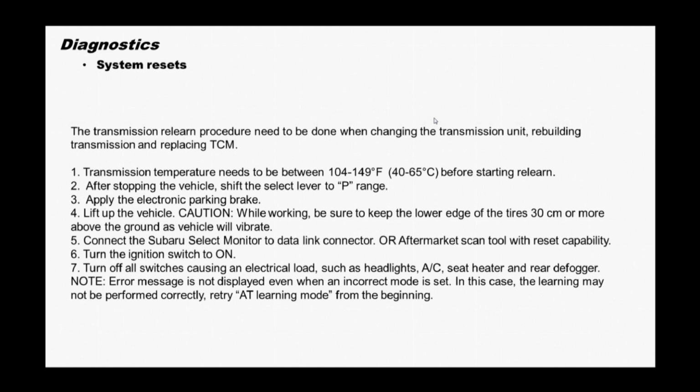Transmission relearn procedure needs to be done when changing the transmission, rebuilding the transmission, or replacing TCM, torque converter, valve body, those kind of things. You definitely want to do a relearn after that. Transmission needs to be 104 to 149 degrees Fahrenheit. If it's not within that range, it will not do the relearn.